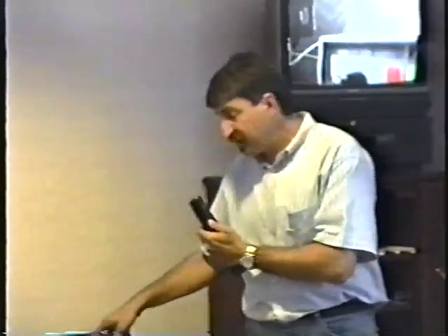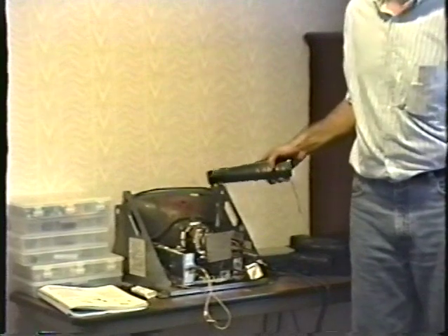when you pull the monitor chassis off, let's say you've set it on the bench to work on it, or you're swapping chassis out in the field because you don't really want to do much monitor repair in the field, you simply want to have a spare if you have one and swap it. After the monitor's been sitting for a while, the picture tube mysteriously recovers some of its charge. This is really important. Just because you've discharged it once and removed the second anode, don't go sticking your tongue in that hole down there. That thing can recover some of its charge.